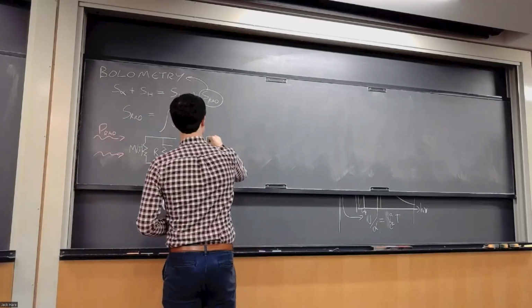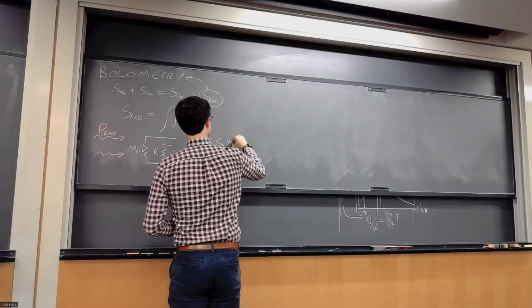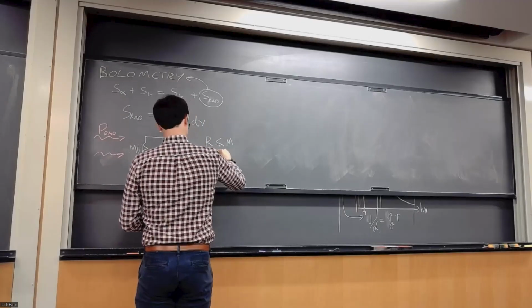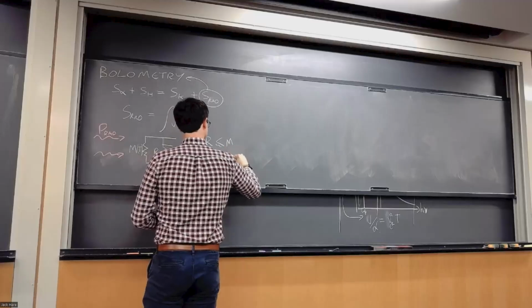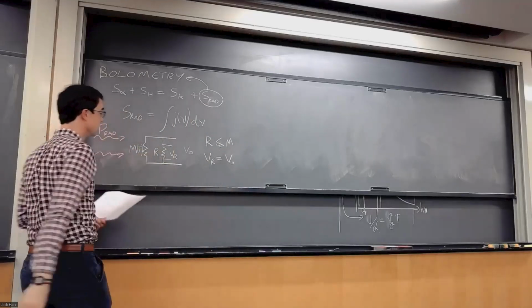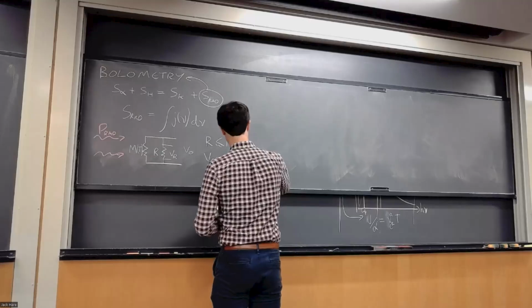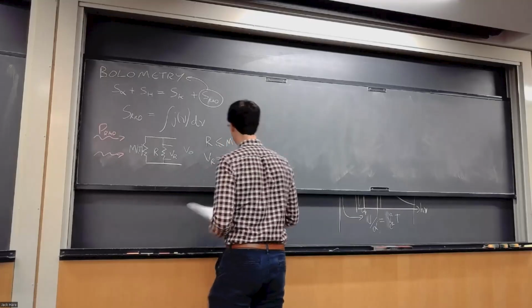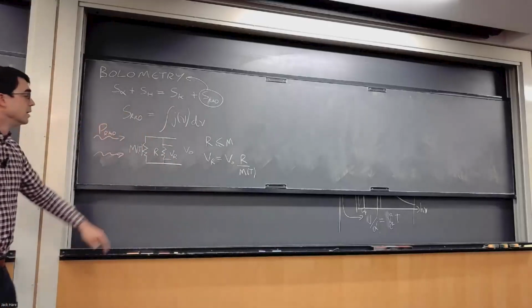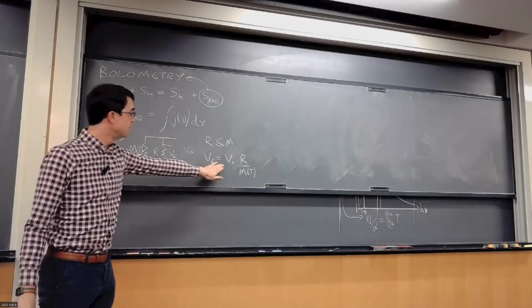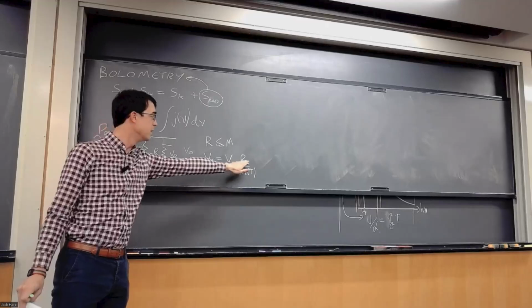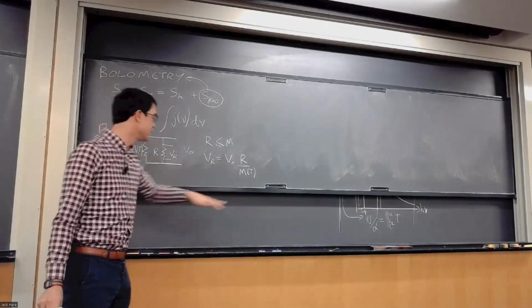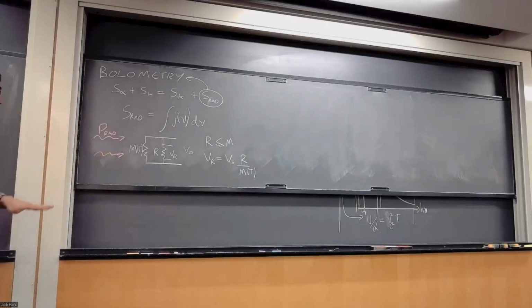We'll choose R to be less than or roughly equal to M, so it doesn't dominate this measurement, and the voltage that we measure, V_R, is equal to whatever voltage we used across all of this system, times R divided by M. So by measuring this voltage V_R, by knowing the voltage V0, by knowing the reference resistor R, we can measure the resistance M. This is a very simple resistive divider, just drawn in a complicated way.